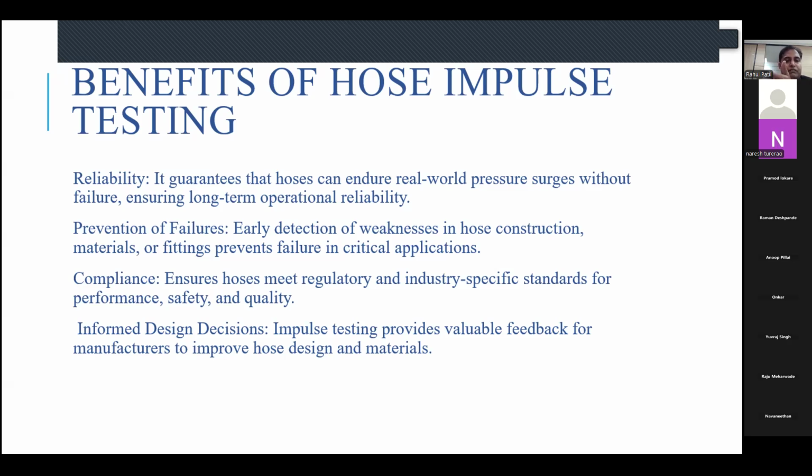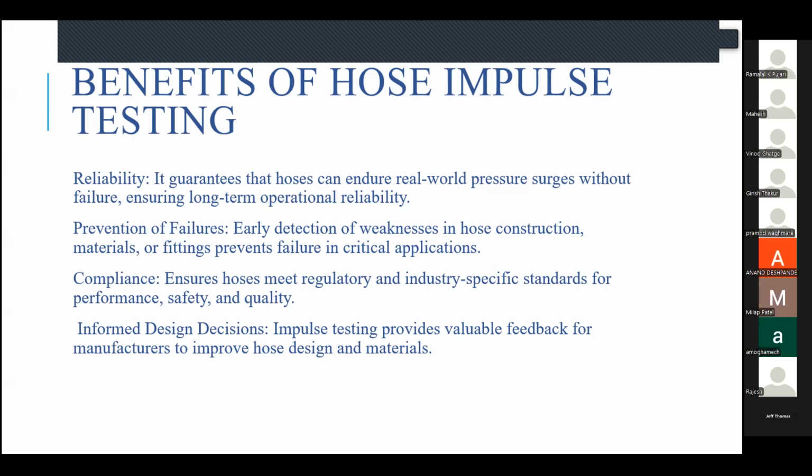We can do the failure prevention, and of course, as far as the compliance part is concerned, there is a mandatory requirement by the OEMs or system integrators that hose should undergo this much testing or impulsation, and we are pretty much assured that the hose has been tested with respect to the laid down criteria, so it can perform very well. Apart from the specified standard, one can design specific hoses, and one can take an informed design decision throughout the impulsation testing that my hose needs certain improvements, or that my hose is specifically not over-designed to the required standard. That way we can definitely give you feedback about the hose development stages.